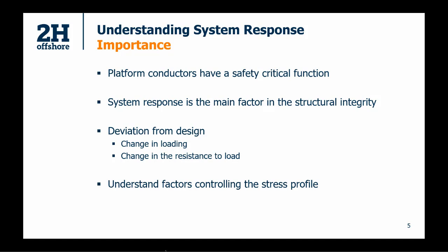Because the system response has such an effect on the well integrity, it's important to know that if you look at the integrity for the as designed system, and you are then looking at a system which in reality deviates from that design, then you're not necessarily looking at the system response of your actual as-built system. So it's important to consider if you have any deviations from the design, whether that's a change in loading or a change in the ability of the conductor to resist the load. So that could be if you see corrosion significantly higher than you were expecting, that loss of wall thickness in your conductor then changes its ability to resist the load. So to understand the stress profile and what's controlling where the integrity problems are likely to occur in the system, we need to understand the factors that are controlling that stress profile.